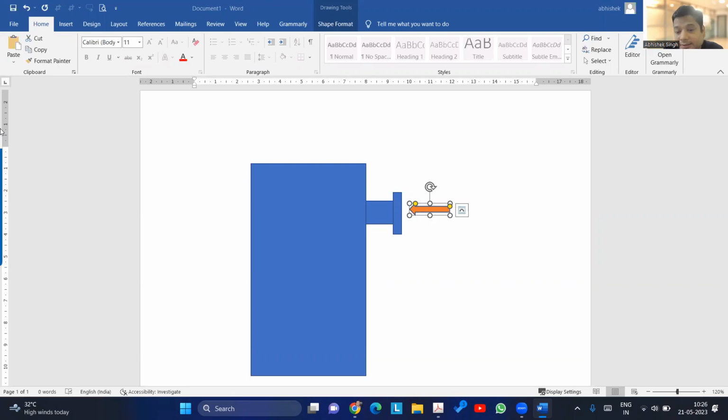Sir, code actually says to consider these external loads. It is not saying that we have to perform WRC or any other method. It's saying to consider this load. Correct. So from engineering practice, we perform the WRC, and if it's within the allowable limits of WRC, fine. If it's not, then we go for FEA. This is for the nozzle to shell junction, the stresses on the nozzle as well as on the shell. And for the flange, we perform the derating. Correct.